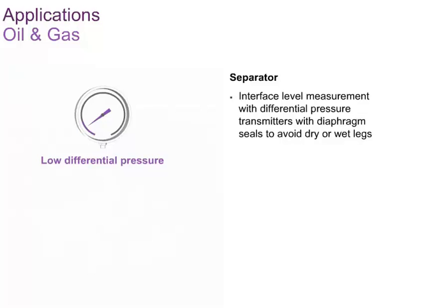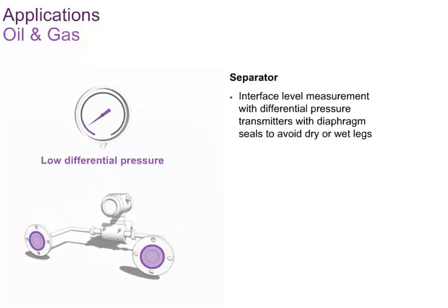The preferred connection method for differential pressure transmitters is via diaphragm seals. These are easy to install and avoid problems which could be caused by liquid-filled impulse lines, called wet legs. For example, bubbles in the filling of these lines, etc.